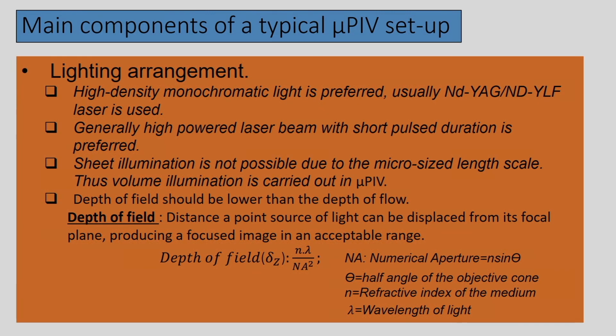Now, if the flow velocity is sufficiently large, then to ensure that the same particles will be there in the second frame of the image, the duration between two successive light pulses will be very small. So that is why a short pulse duration of the laser is preferred.